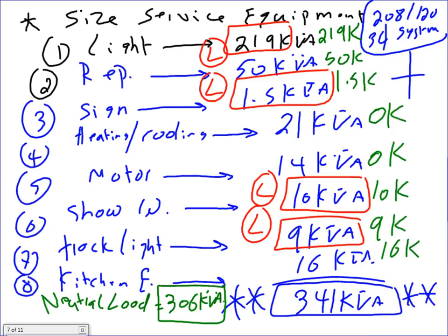Kitchen equipment, no. I'm going to put them in a different panel, on the receptacle panel. Most of the time, guys, kitchen equipment, receptacle panel. By the way, right here, you can size 3 types of panels: lighting panel, receptacle panel, and mechanical equipment panel. That's what most of the time in the commercial building they have. You can do the rest as an exercise, but I'm going to do only the lighting panel. Only the lighting panel will size it.